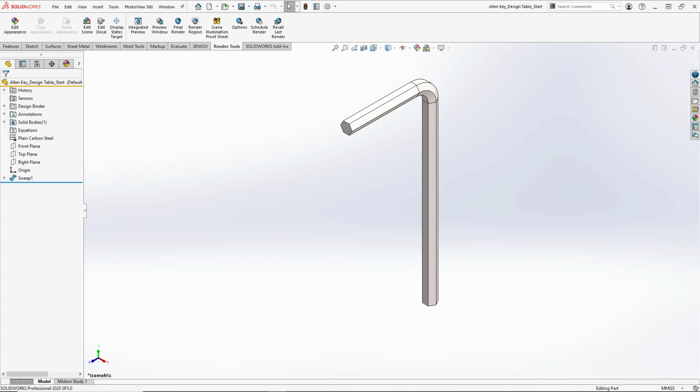We name the dimensions so SolidWorks will flag them for capture when the design table is created. First, we'll click the Show Hide drop-down, which is the creepy little eyeball up here, and we will select this D1 icon, which will show our dimension names.